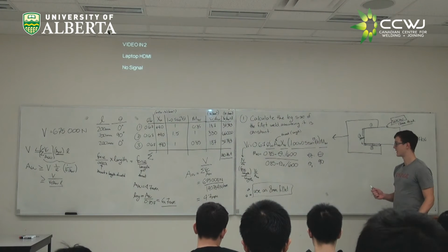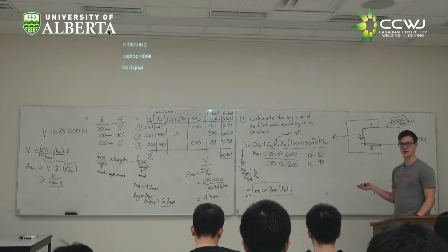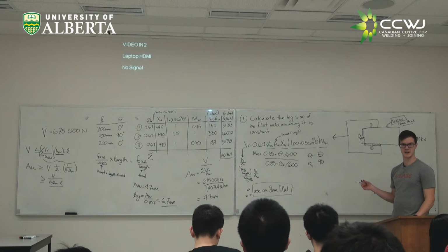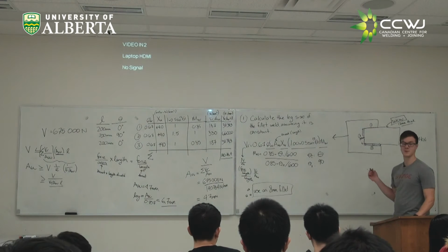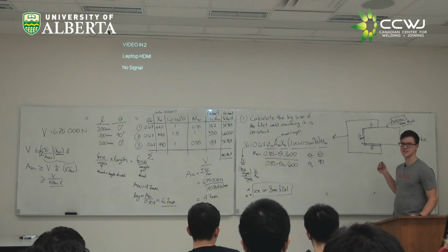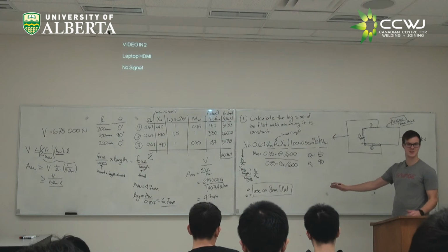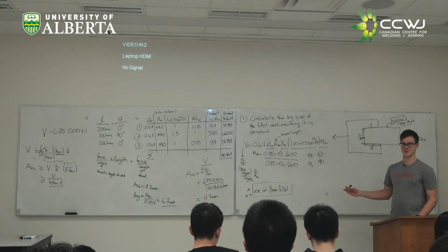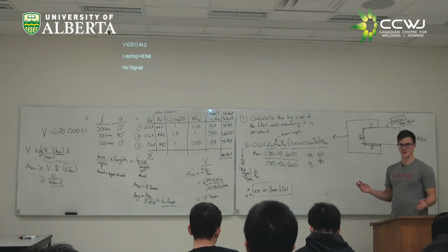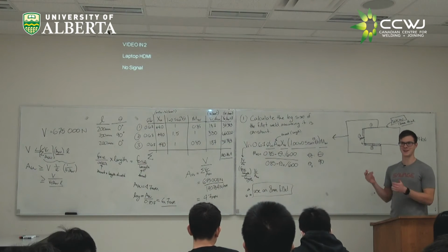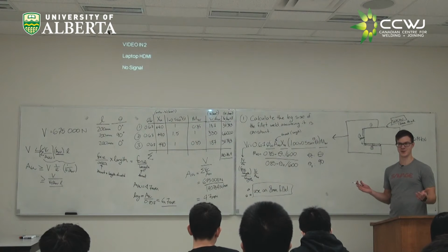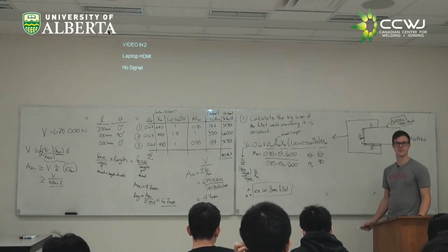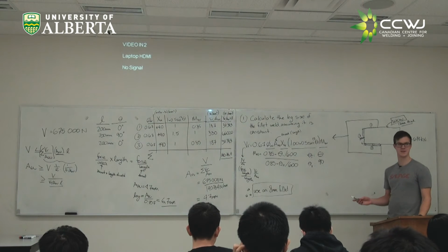Now, one thing, if we were to go back and check, we talked a little bit about what our minimum and maximum sizes were per CISC. Our min was 5 millimeters, our max was T-2, 10 millimeters. This is between those two, so we don't have to do anything further. If this was greater than our maximum, we have an issue because we can't make a weld that's big enough to handle the load, so we got to redesign the structure. If it's less than our minimum, we don't have an issue, we just round up to our minimum size. Does that make sense to everyone?